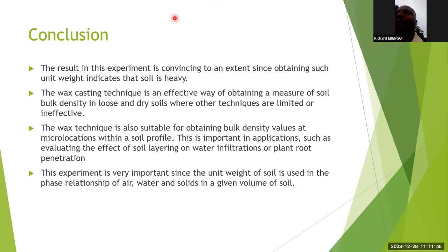There you go. Okay, I have a question. This subject is very interesting for me because we have found difficulties measuring the compaction of sand. We are building the ring wall and have to fill it with sand, but that sand is river sand, so we can't do a Proctor test to measure the compaction.